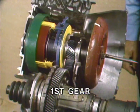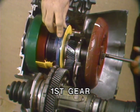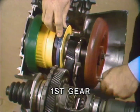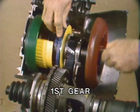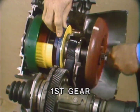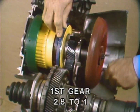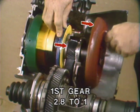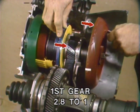Again, let's see it on the hardware. This time, Joe is tightening the band around the forward sun gear drum, and he will again drive the turbine shaft. Now, as you can see, the planet carrier and final drive input gear are turning the same direction as the input shaft, but at a reduced speed. In first gear, the ratio is 2.8 to 1. Count the turns of the turbine. 1 turn, 2 turns, almost 3 turns.